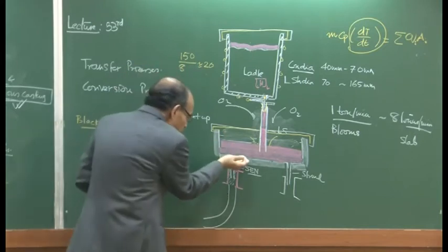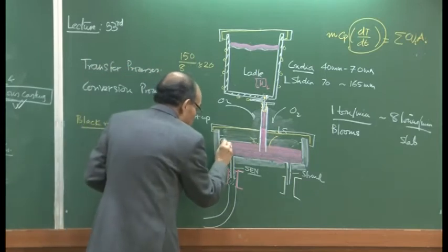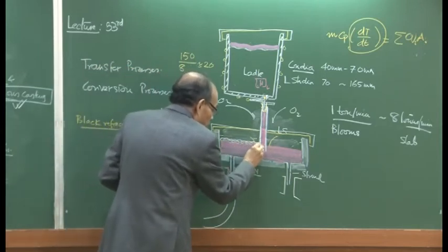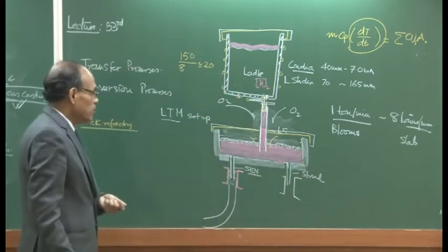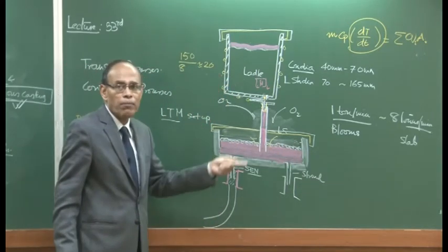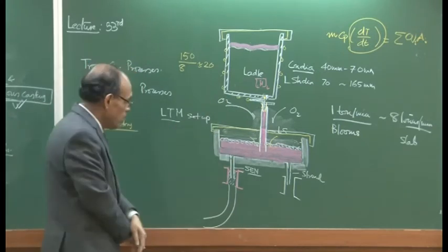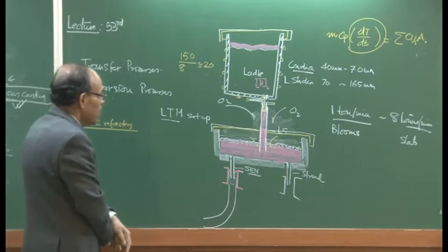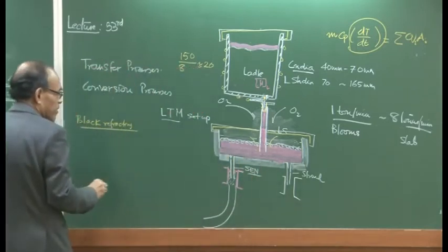So, as the tundish is filled, we add what is known as a tundish powder, and this tundish powder is going to protect the steel. The tundish powder has two different purposes. It will immediately produce a cover, preventing any further contact with the atmospheric air. These powders have two different characteristics.